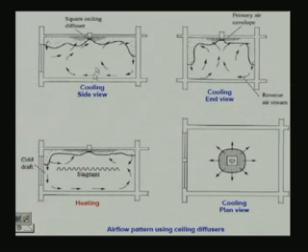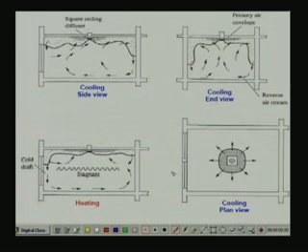Let me again show the airflow pattern when used for cooling. This is the side view. This is where you have the primary air and this is the diffuser. It first sticks to the ceiling because of the Coanda effect, then entrainment takes place and you have the total air here, then the reverse stream starts like this, and there is again hardly any stagnant area when you are using it for cooling. Similarly, this is the end view and this is the plan view.